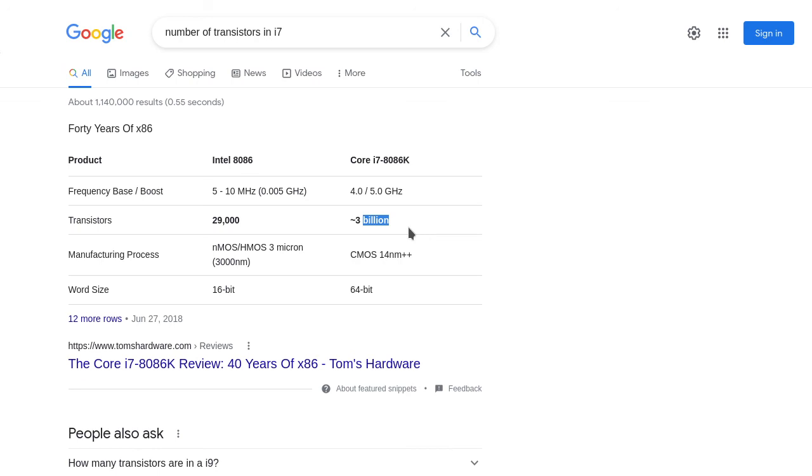Well, okay, so the transistors are called FETs, for field effect transistors. So they have an insulation layer in here, and then there's another substrate material here. So this is supposed to be an insulator, which is also why we have the metal oxide, because the metal oxide is what we use as the insulator. So in MOSFET, the MO is metal oxide, and that is used as the insulator.